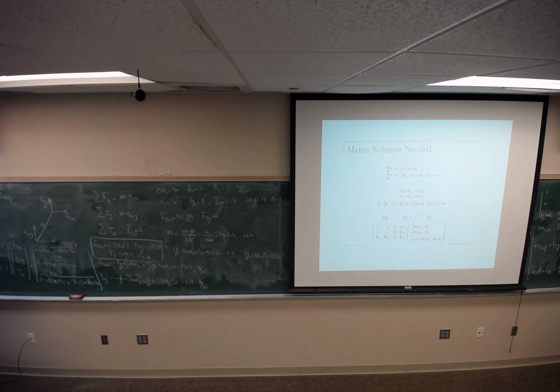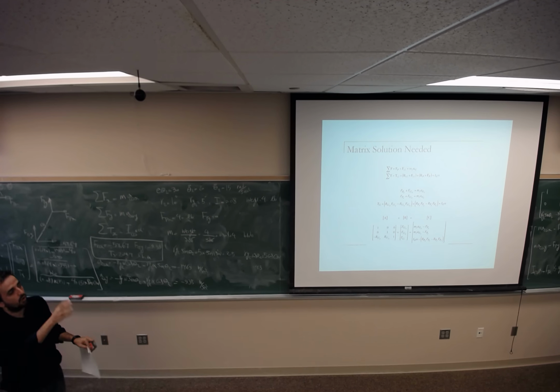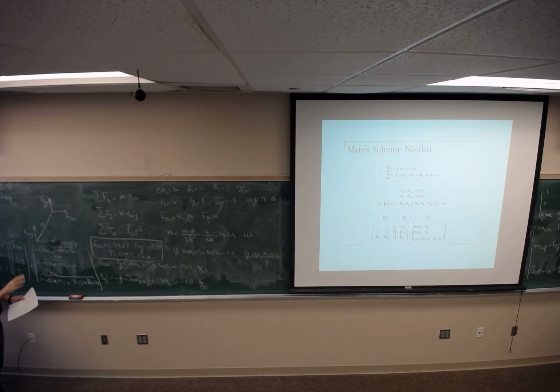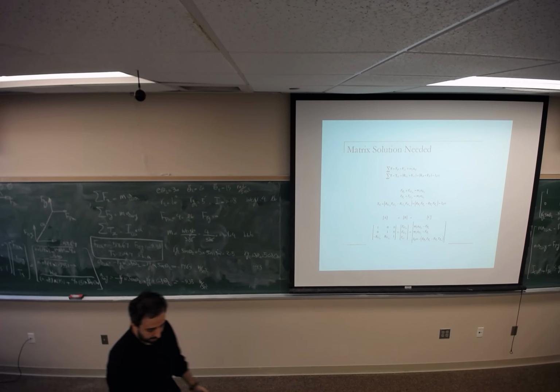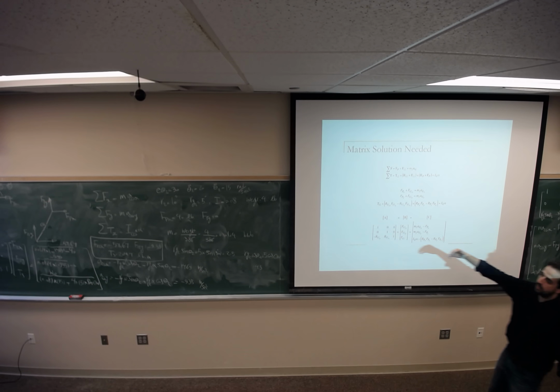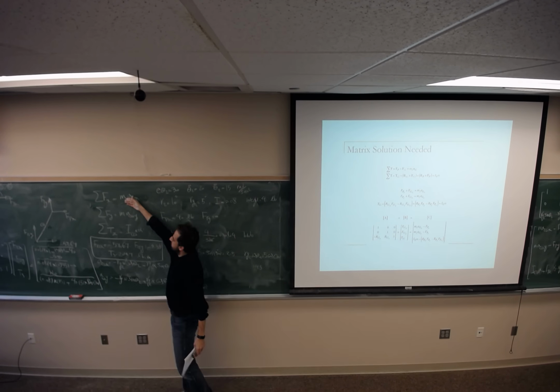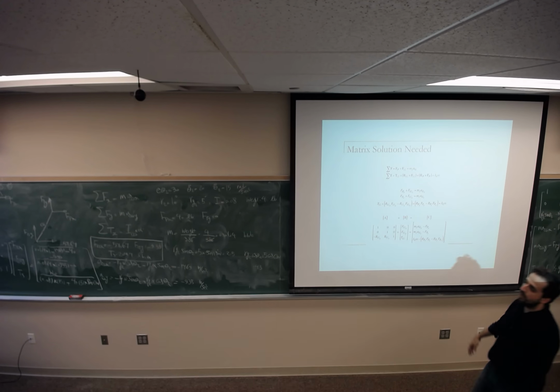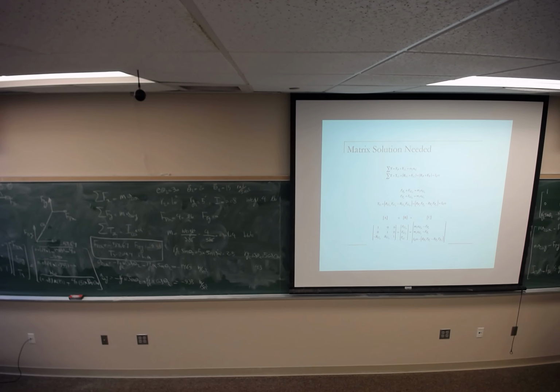So make sure that you know the steps, because in the next homework you need to write code to do force analysis for a 4-bar mechanism. It's just for one link. The next step is we extend this to the 4-bar mechanism. We are going to rewrite these 3 equations for 3 links, so we are going to get 9 equations. This 3 by 3 is going to change to 9 by 9.